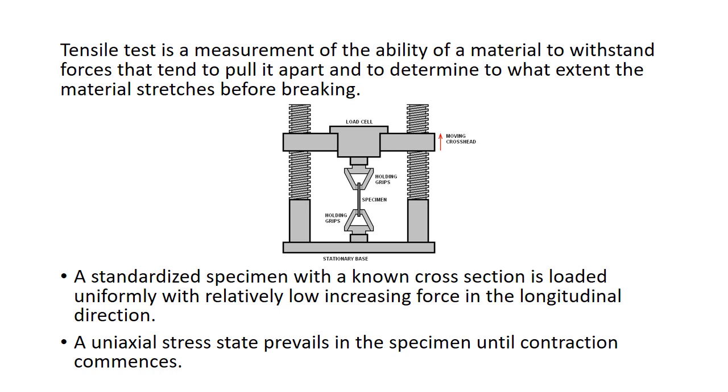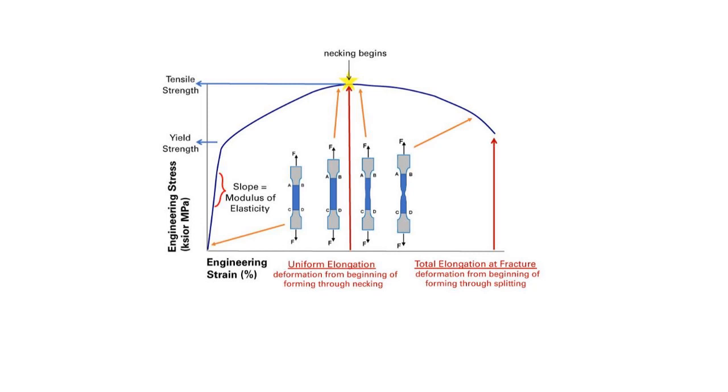Universal testing machine. The universal testing machine has two cross heads, one of which is adjusted for the length of the specimen and the other is hydraulic power driven to apply tension and compression to the test specimen. It is capable of a force capacity from 500 Newton to 1 meganewton. The strain is measured with an extensometer. The extensometer calculates the dimensional change by attaching a sensitive measurement device to the test piece. The device is used to measure longitudinal strain.